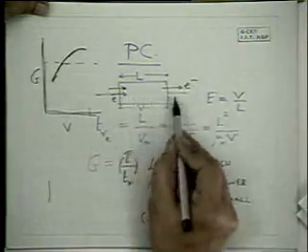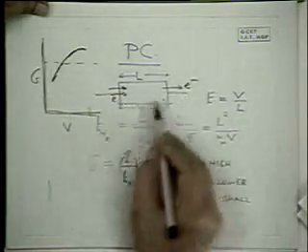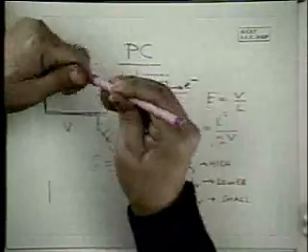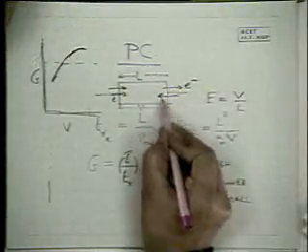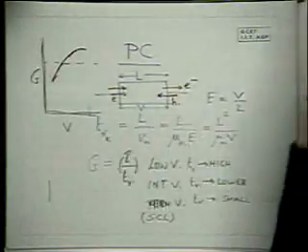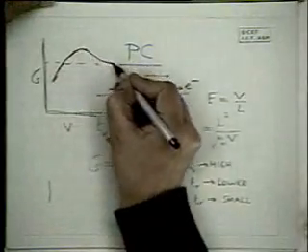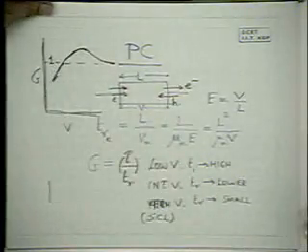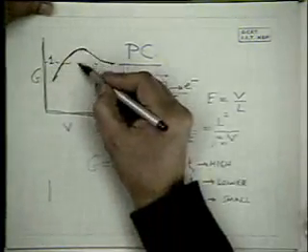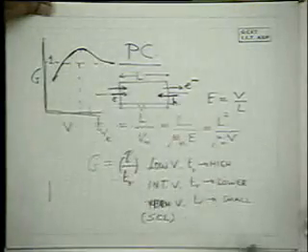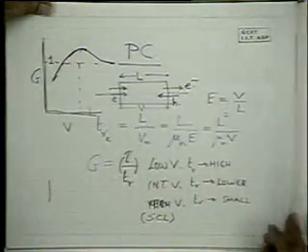When high injection of electrons takes place from one electrode and injection of holes takes place from the other electrode, the gain reduces to 1. So there is an intermediate range of voltage at which the photoconductor shows maximum gain.